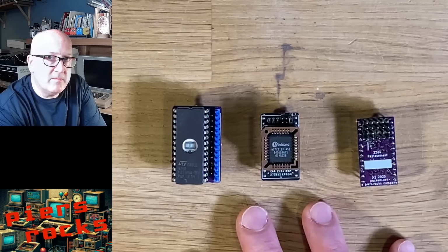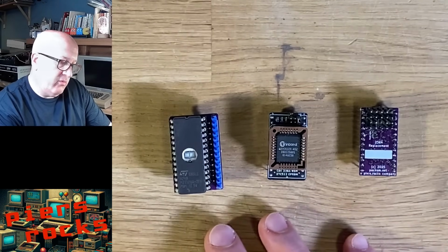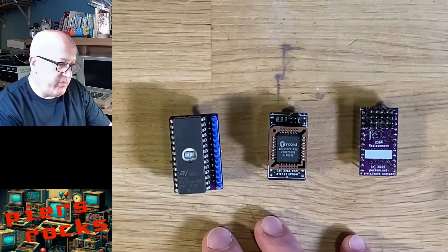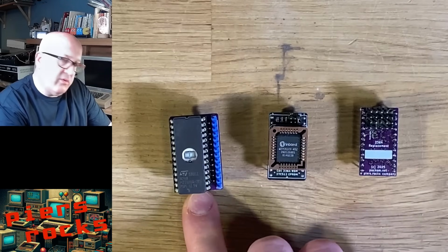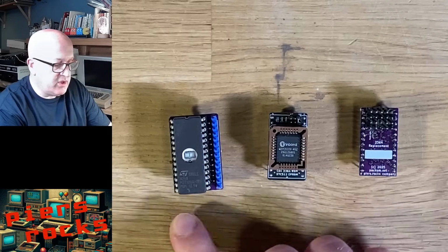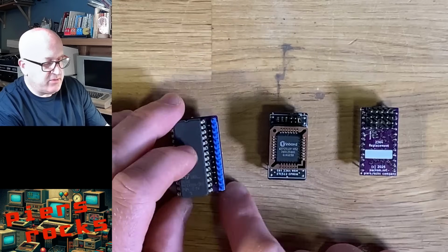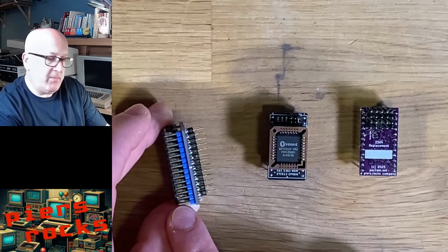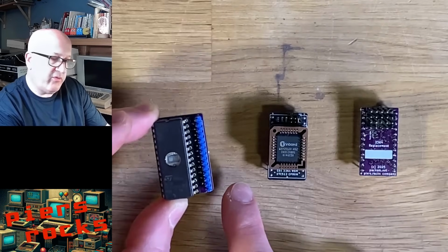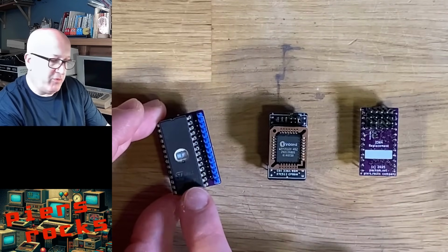That's pretty inflexible. So the second issue I have with common ROM replacement boards is that they're tedious to reprogram. We look at this replacement board as an example. This is probably the most common type of ROM replacement boards. It uses an old stock 27 series EEPROM, and the replacement board essentially just maps the 28 pin down to the 24 pin. To reprogram it, you have to remove this from the host. You then have to remove this chip from the replacement board.